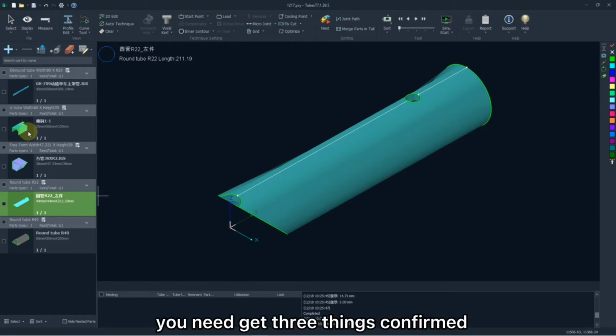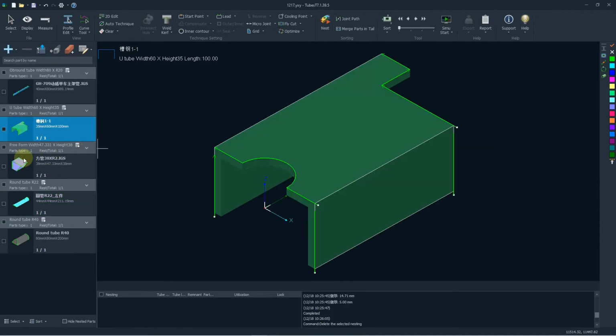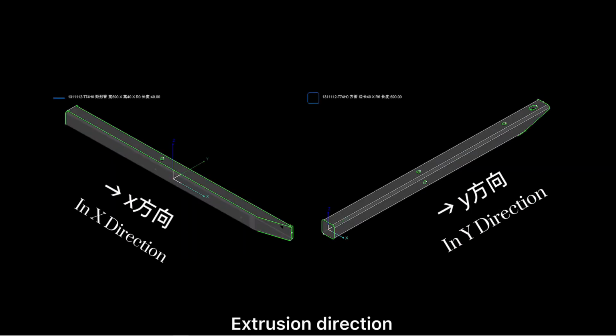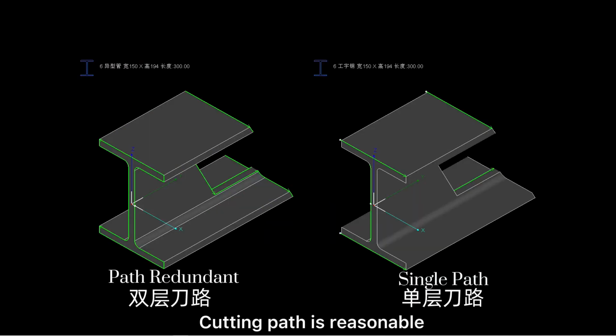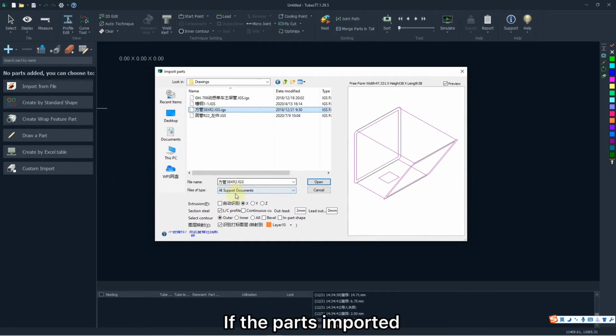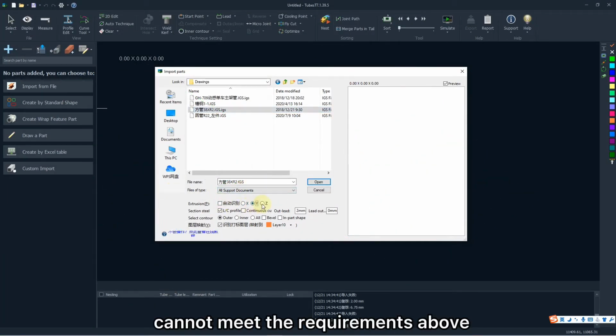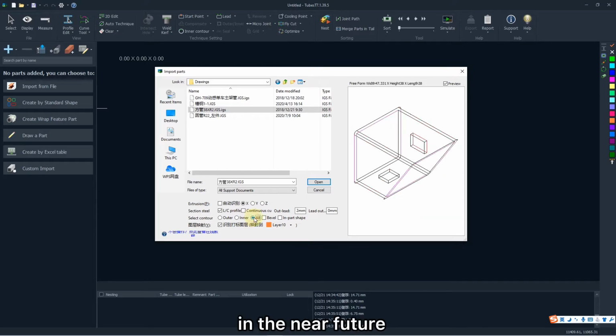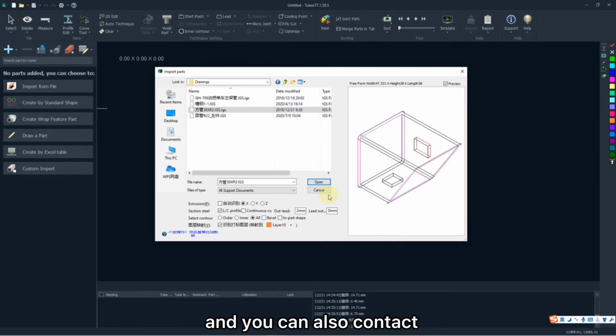To ensure that, you need to get 3 things covered. The section is identified correctly. Extrusion direction is along the y-axis. Cutting path is reasonable. Generally, you need to check that there is no redundant cutting path. If the part imported cannot meet the requirements above, maybe there is something wrong in the import interface. More details on it we will talk about in the near future, and you can also contact us by email